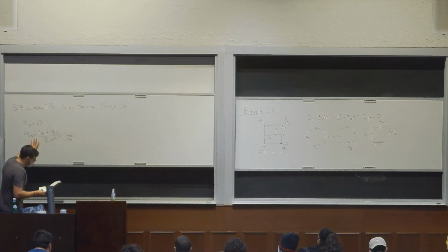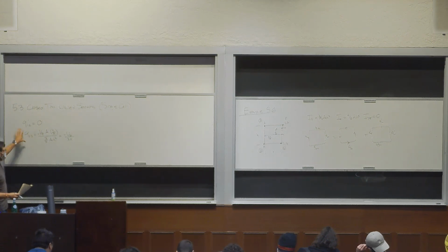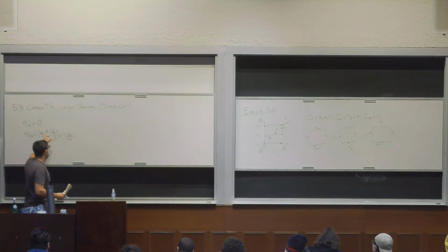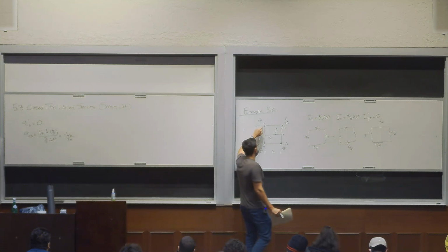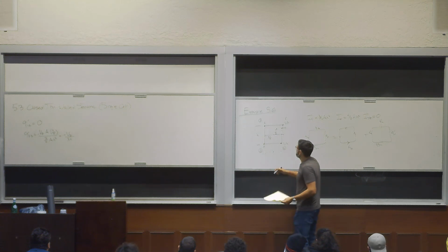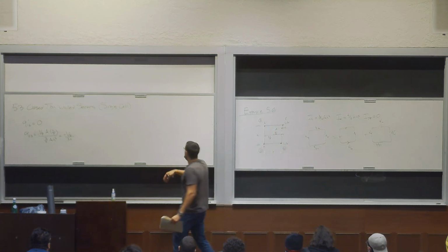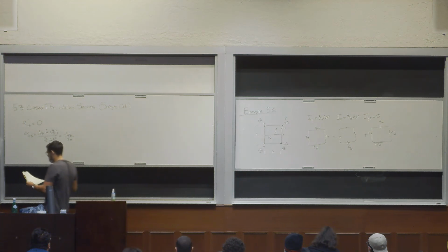Am I missing some? Negative VZ times Q over IY. Q here makes sense, right? It's A times the Z position of the centroid of this, right? So we've made the cut here. This is the only one that matters. Z position is H over 2. Then IY, we calculated it, 3/2 AH squared. So simple enough.